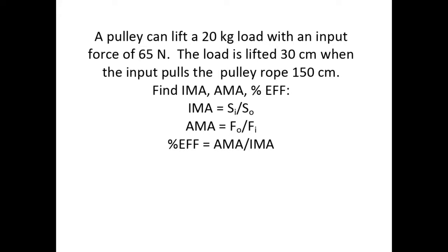A pulley can lift a 20 kilogram load with an input force of 65 newtons. The load is lifted 30 centimeters when the input pulls the pulley rope 150 centimeters. Find IMA, AMA, and percent efficiency. And those are the formulas you're going to be using.